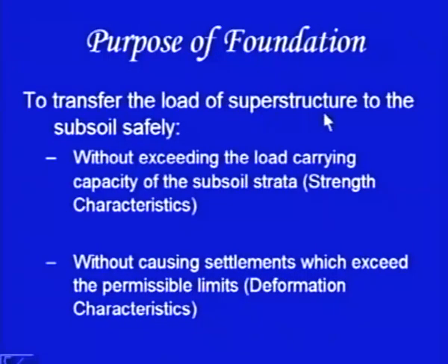When we say superstructure, it means the structure which you can see, and the purpose of the foundation is to transfer this load from the superstructure to the subsoil. Subsoil means the ground which is under the foundation, and the purpose is to transfer this load safely. When we say safely, it means the load should not exceed the load carrying capacity of the subsoil strata. This is termed as strength characteristic, and at the same time there is a second requirement which we would like to confirm, and that is it should not cause settlements which exceed the permissible limits.